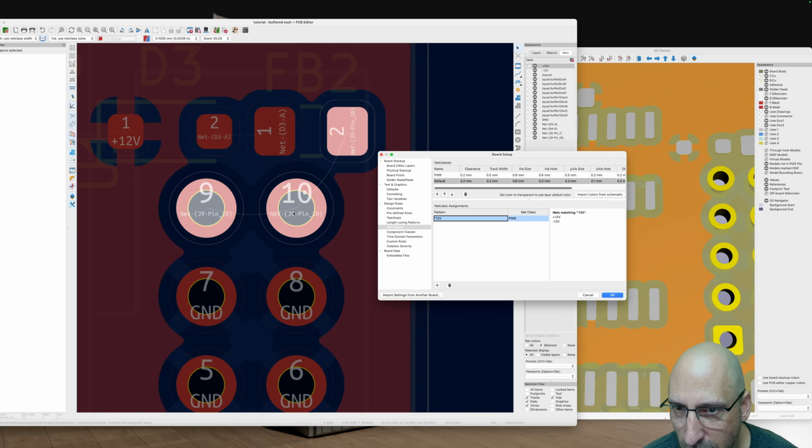I also need to include this net. So it's, I guess it's jumper 9, which is our connector, J9. So I could say net dash J9 star. So now it selects J9 pin 1 and pin 10. So this is J9 pin 10. I can't move around, but pin 1 obviously is on the bottom.